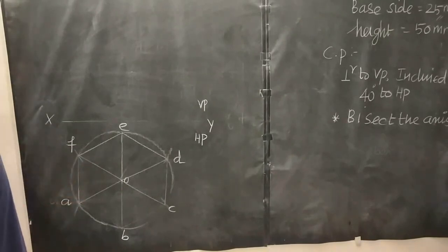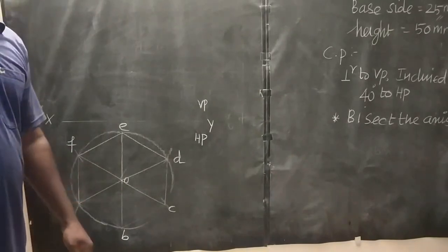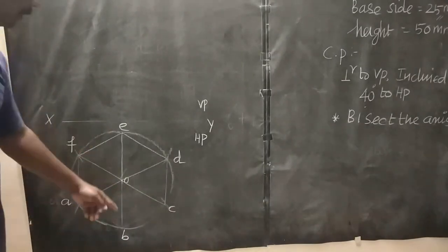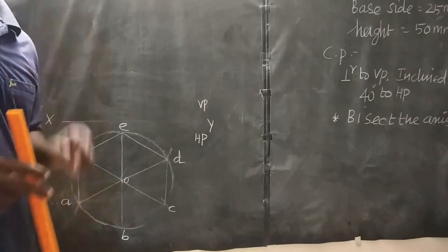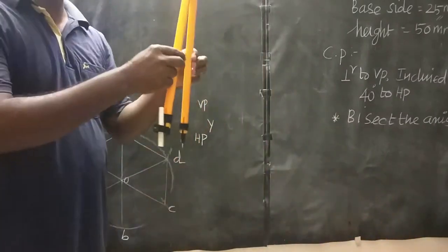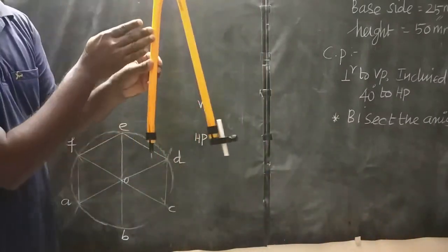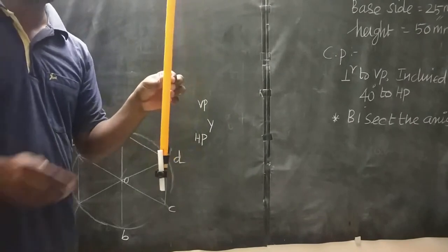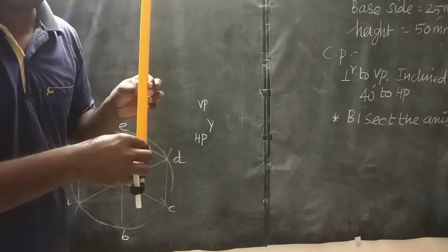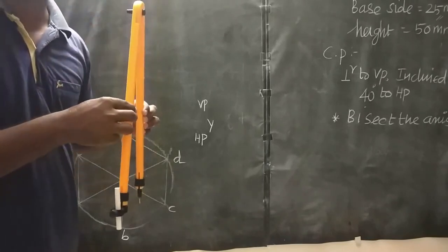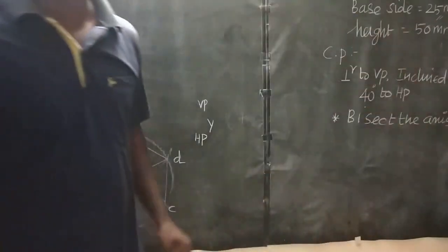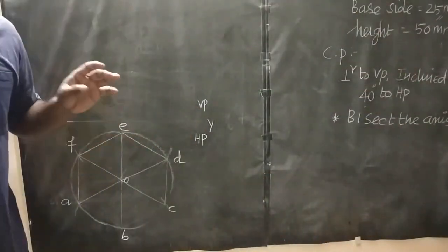Okay. So first of all, here how you represent the axis, that is very important. See here in this problem, the OB slant edge hides the axis of the pyramid. Let's see here. So assume this is one of the slant edges. This is your axis. In a front view, this slant edge hides the axis. So here the slant edge is visible. So give more priority to the visible boundary. So here draw the axis as a continuous thin line. Okay, don't use chain thin line.